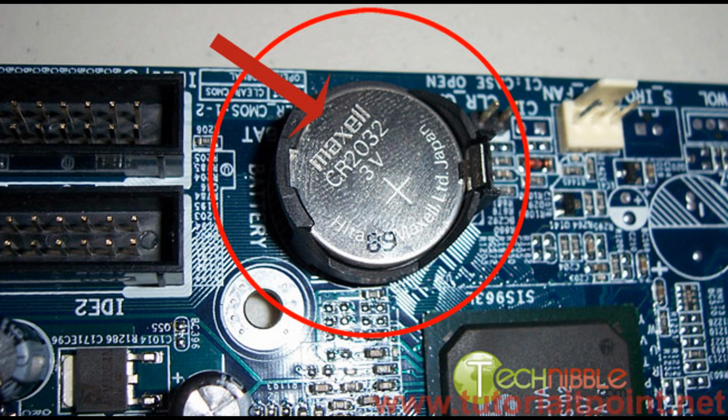This complementary behavior ensures that there is a direct transition between high and low logic levels without any intermediate states, resulting in efficient and robust operation. Logic gates. By combining NMOS and PMOS transistors in various configurations, CMOS technology can implement all the fundamental logic gates such as AND, OR, NAND, NOR, and XOR gates. Each gate exploits the complementary behavior of NMOS and PMOS transistors to achieve the desired logic functionality while minimizing power consumption and ensuring high noise immunity.